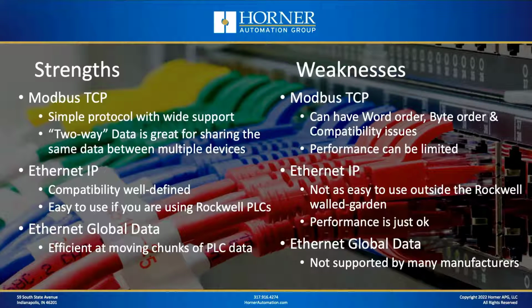And because it is a relatively simple protocol, it can have compatibility issues because they didn't think it was complex enough to have a body that does any kind of significant certification. So compatibility issues can happen with Modbus. And because it is a pull response type protocol, when you get a bunch of units talking to each other using that protocol, performance is limited. The type of response times that you can achieve are limited.